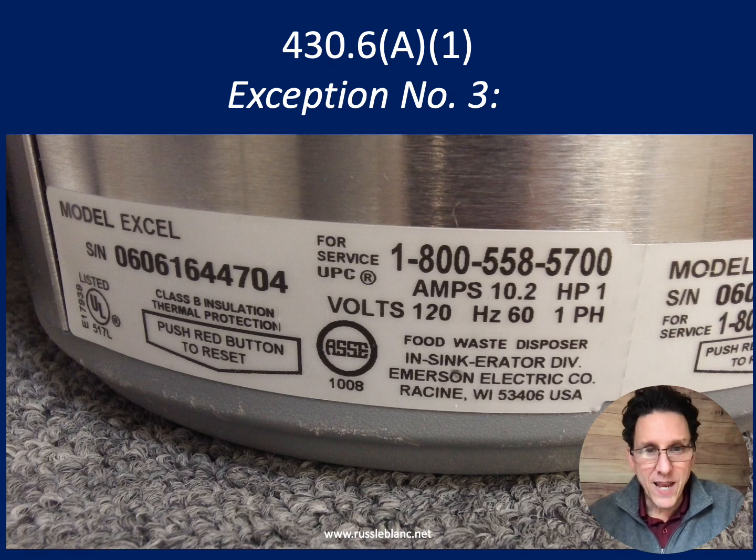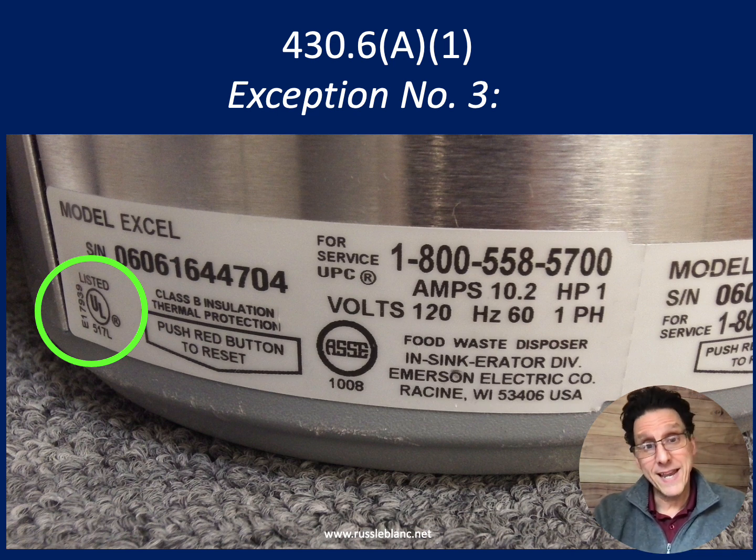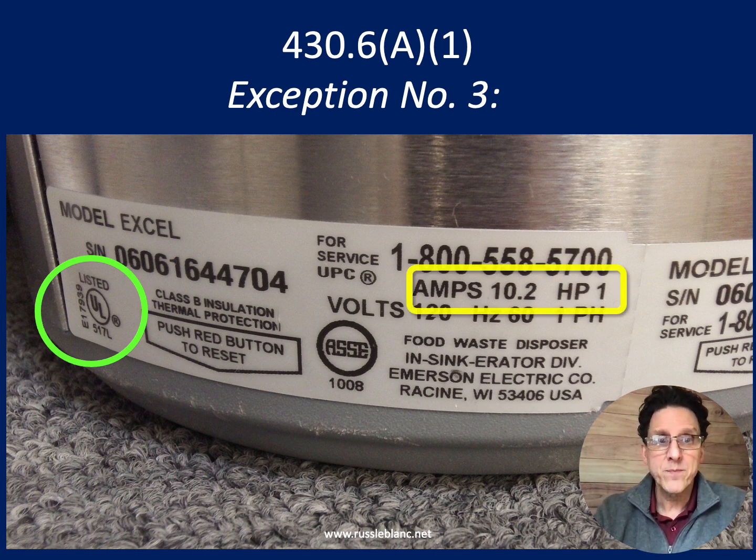Okay, here's a nameplate for a garbage disposal. It is listed, it's required to be listed, and exception 3 says if it's listed and it's marked in both horsepower and amperage, then we can use the amperage on the nameplate instead of going to the code book tables. And there it is, it has both amperage and horsepower, so we can use that. The 10.2 versus the 16 from that first motor I showed you, that was also a 1 horsepower motor, but in that case we had to go to the code book tables, and it said 16 amps. That's a big difference, 10.2 amps versus 16 amps.